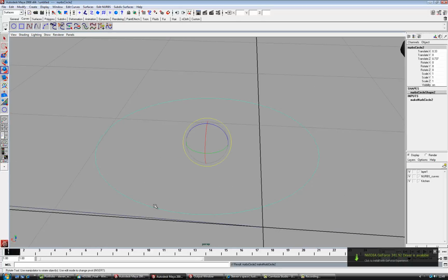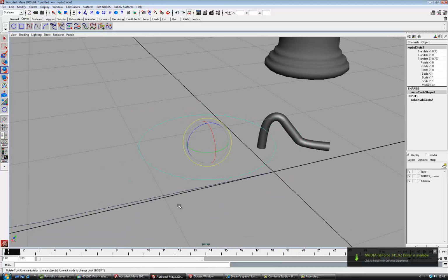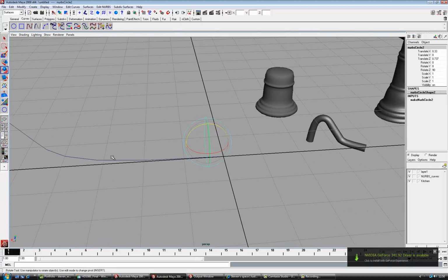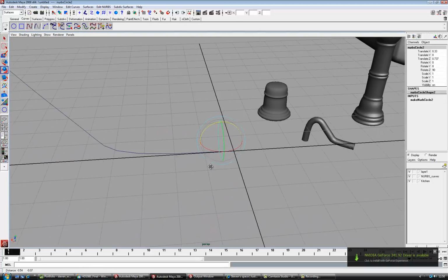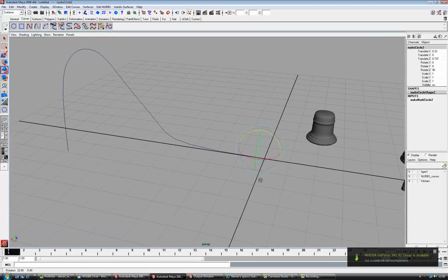Frame up. Bring up the rotate tool with E. We can see that the dimension that I want to rotate it in will be the blue line, this one here. And you can see that rotate Z in the channel box changes as I modify that value. So just watch Control Z, that changes. I want to move that to 90 degrees. It works in degrees in Maya rather than radians. Degrees are a lot easier. Everybody knows how to use them from school and stuff.